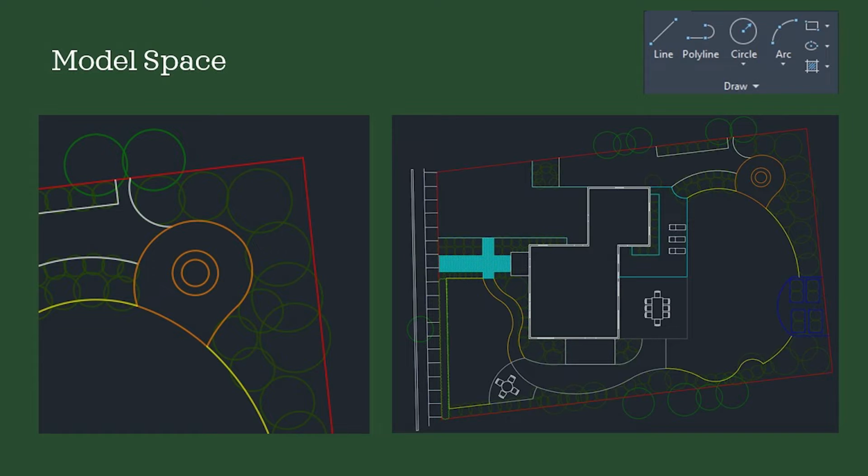The three-point arc was used to create all the curvilinear lines, including the proposed front walkway, fire pit area, and mulch bed lines. The three-point arc is used by selecting the first point, estimating the middle point, and then finishing the arc with the placement of the third point. The arcs are not always perfect, but can be edited later on.